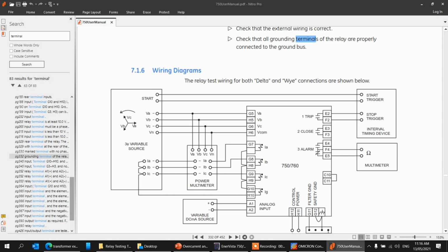So when you say feed from, that means you change the positive connection to the contact. Let's say in our scenario here, E2 is my positive, and on F2 I'm not getting anything because it's open contact at the moment. So I'll put my Omicron contact connections, the one positive on F2, and the other one goes to Earth, without any disconnection.